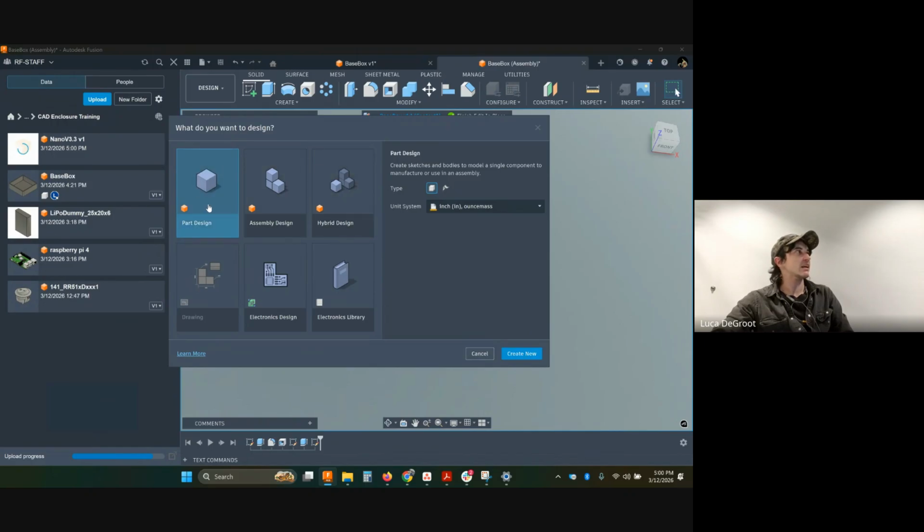It's kind of moving towards more of a SolidWorks approach. It used to be all hybrid, where either you're making parts or you're making assemblies. Assemblies are parts that are all put together. You can do part editing essentially in your assembly design. You cannot make an assembly out of parts, but you could make a multi-body part, which is a part that has multiple bodies in it.